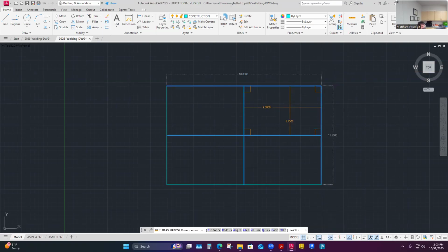This is how I check my stuff as I go, because I don't have it dimensioned yet. I don't know what the dimensions are. I put them in with my fingers, but I could have fat fingered a dimension. When I'm manually entering data with my own hand, I could accidentally put the wrong dimensions in pretty easily. So I have to check myself as I go. Otherwise, a drafter finds they've done stuff wrong when they start to dimension it on the sheets, and that can be pretty painful to go back and correct.